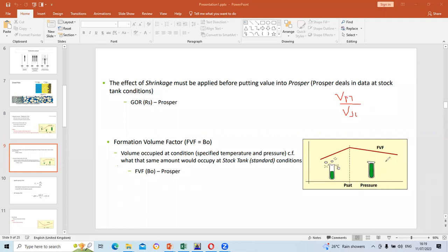All right. So what will happen now is, remember, if this is our PT, if this is our bubble point, above the bubble point, no gas exists within the reservoir. So now, if we are starting at a reservoir pressure that is higher than the bubble point pressure, as you are decreasing the pressure, what is happening is the formation volume factor is increasing.